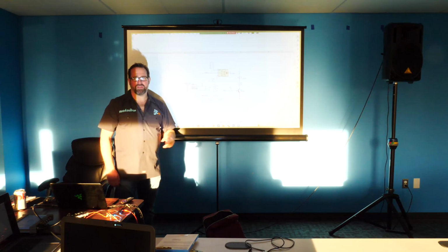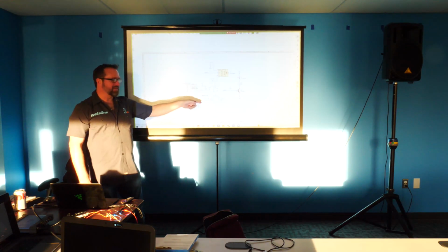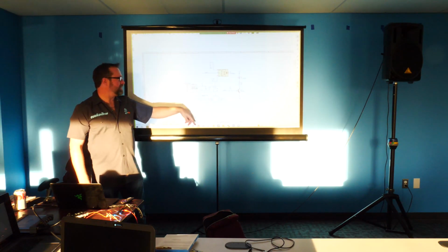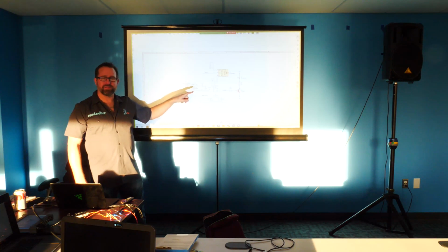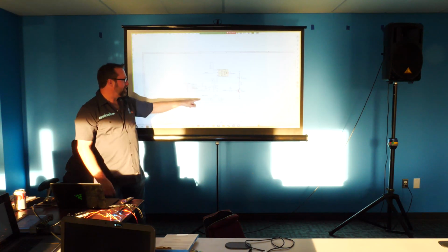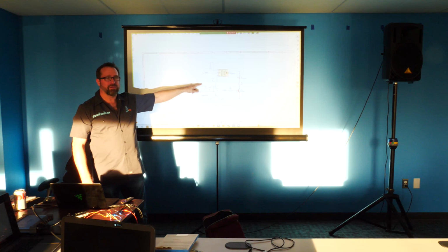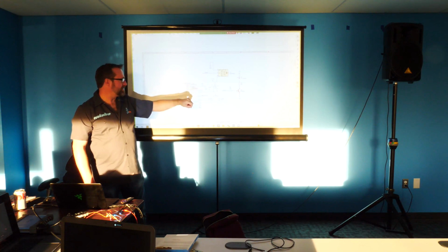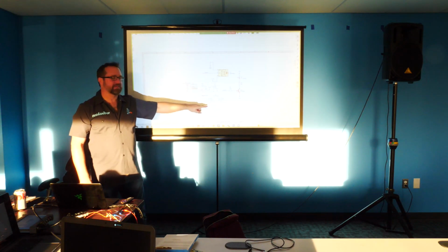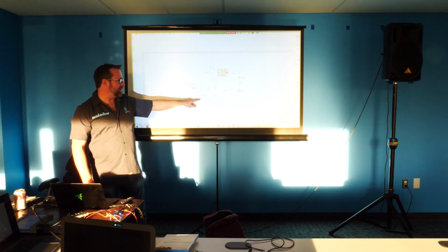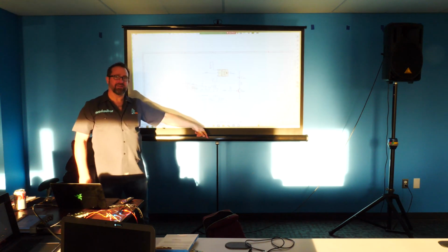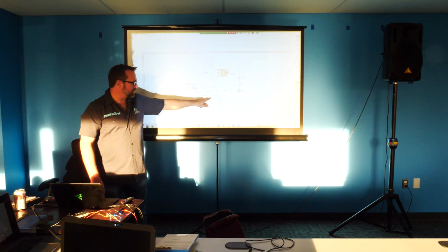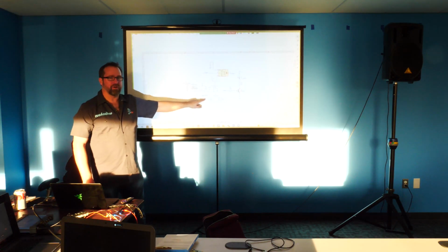Now, if you know anything about electronics, this doesn't really work normally, but the Pi Pico has resistors inside the chip that you can pull this pin up to logic 1 when it's not being pressed. So normally this pin will sit at 1, and then when you push the button, it goes down to ground because it completes the circuit through the normally open connection.